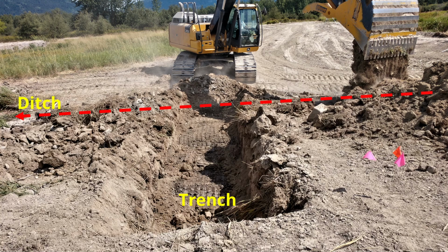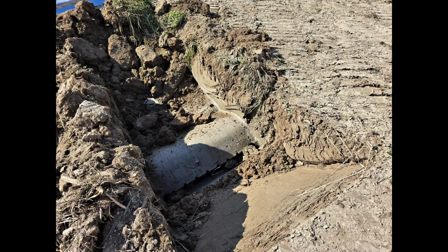You can see the roots that were severed by digging the core trench for the groundwater dam. See how the excavator has cut through the reed canary grass and its roots and down into the clay? I stay on site 100% of the time and carefully watch as the excavator operator digs the core trench for the groundwater dam. I watch and I guide the operator to ensure that we are digging deep enough into an impermeable layer, and the soil that we're using to build the groundwater dam is high in clay.